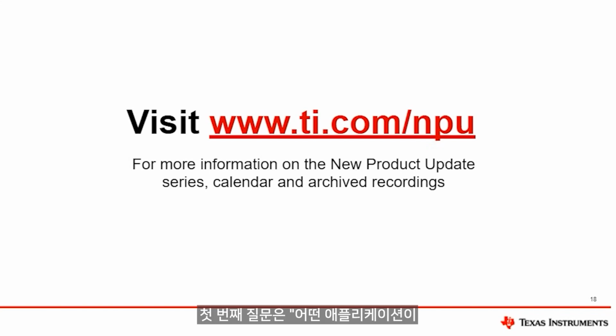The first question is, which application is suitable for a back-to-back FET topology and which application is suitable for a single FET topology? The applications which are suitable for back-to-back FET topology are the applications which require reverse current blocking and reverse voltage protection, and for the single FET topology, it is majorly overcurrent protection, overcurrent limiting, and overvoltage protection.